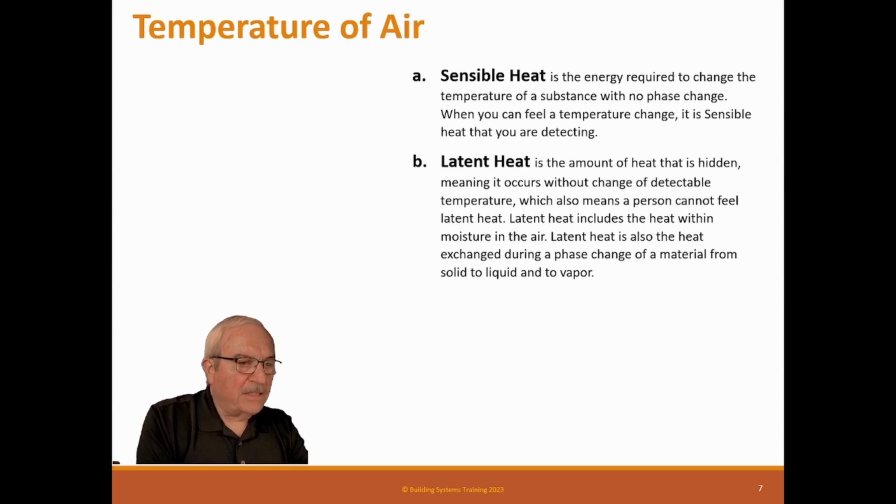Latent heat is actually the heat of the moisture in the air. It's also the heat when water goes from liquid to steam, and when water goes from liquid to ice. That's latent heat change. You can't actually feel it. Now, you can feel the results of latent heat. So if it gets real humid outside and the water in the air has latent heat in it, you feel its effect. You don't feel it directly, but you can feel its effect.